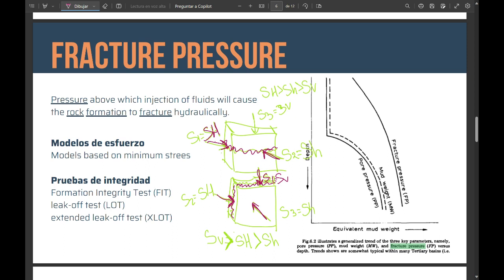or as also known, integrity tests, that are like the intermediate or production wellbore sections when they are drilled or cased and cemented with steel tubular pipes. They are going to provide the required well and barrier integrity demanded to safely protect the well from failing during its life cycle. So the planning, design, and engineering of each wellbore section is decided through determining and evaluating an optimal safe setting depth range, of how shallow or how deep it can be set.